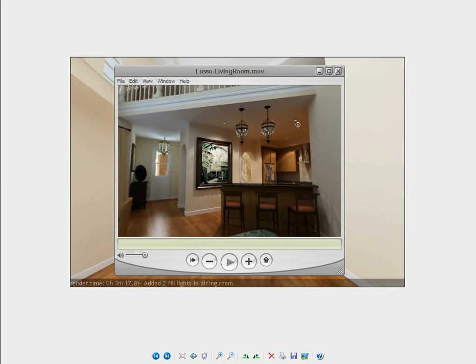So even if the client wants changes to the furniture and wants to change the lights, I don't have to worry about that because these ceiling fixtures are very unlikely to change. Any changes to the client's choice of lamps or hanging fixtures can affect the illumination provided if I light the kitchen using lights where these fixtures go. So with all that considered, I've decided that I'm only going to light this kitchen area using artificial light placed in the ceiling lights here.